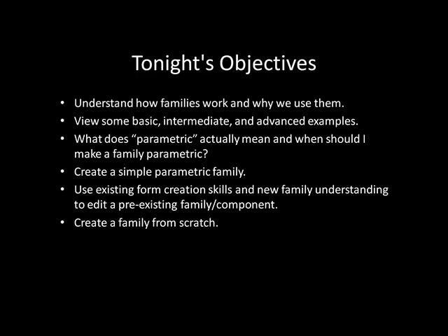Basically, we call it parametric if it has the ability to change. So if you can change the materials or change the size of the family, then it becomes parametric. Versus, say, a one-off chair, which has no different sizes, has no different finishes. It just is a wooden chair. It can't really change. That would be a non-parametric family. But then the same table, which can have different sizes and different finishes, like glass versus wood, or different heights or different depths, that would be a parametric family.